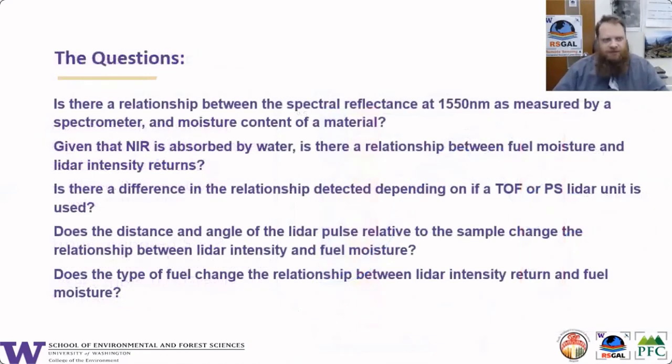So for this study, we had a whole host of questions that we wanted to ask. Is there a relationship between the spectral reflectance at 1550 nanometers, as measured by a spectrometer, and the moisture content of a material? Given that near infrared is absorbed by water, is there a relationship between fuel moisture and LiDAR intensity returns? Is there a difference in the relationship detected depending on whether a time of flight or a phase shift LiDAR unit is used?